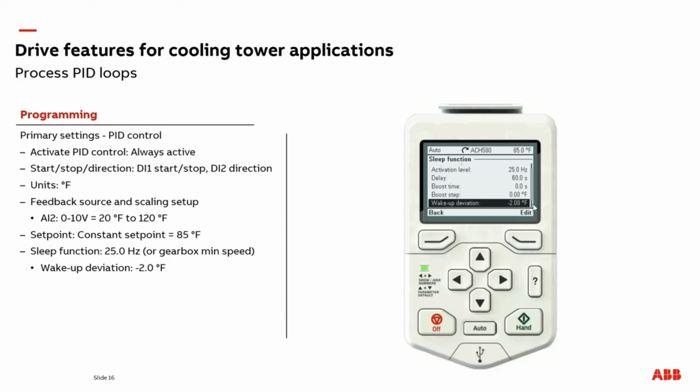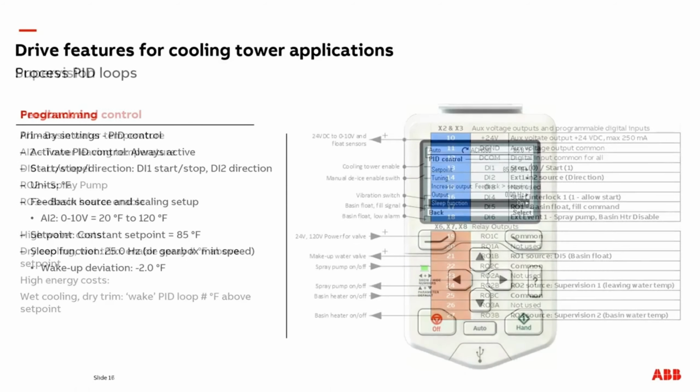At negative 2 degrees from the sleep function and the set point, we have about a 2 degree dead band as well, where it'll either stay awake and run or stay asleep if coming down. That should be it for the PID control.